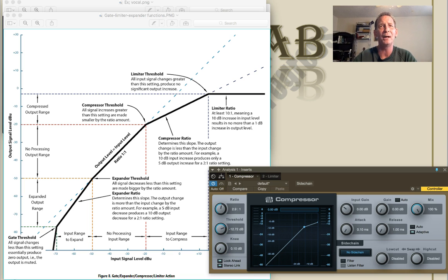And your hard and soft knee is a real simple concept. Normally a hard knee is what I start with, and they say it's good for harder sounds like drums. The soft knee introduces gain reduction gradually as the signal level increases and approaches the threshold. They say it has a much more transparent effect. You just have to mess with that. It's whether the compression hits all of a sudden, or comes in a little softer, sloping into it and doing the actual compression.